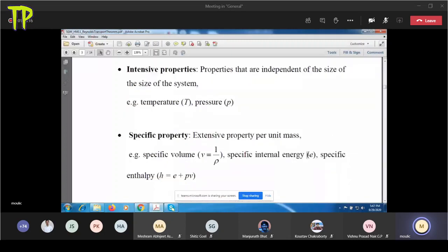Of course, quite often in thermodynamics texts, it will be expressed in kilojoule per kg, otherwise the number will be very large. But when you solve problems, you have to convert it to joule per kg, otherwise the numerical answer may not be correct. You have to make sure that the units of each term in the equation are the same.